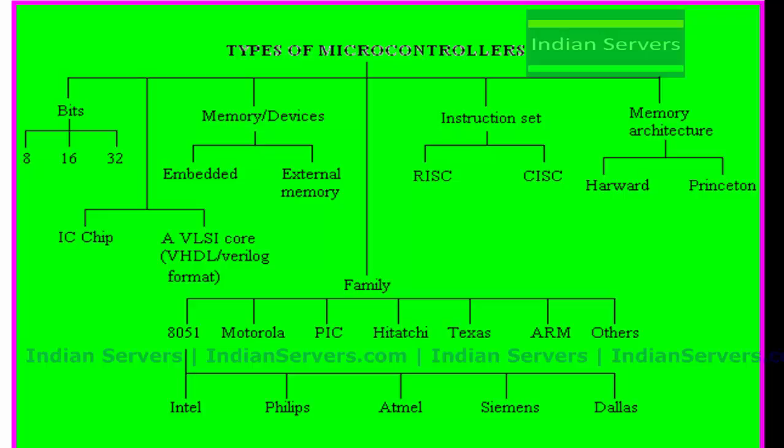Coming to RISC, we can easily program a controller or an embedded system. The instructions are very easy to understand. If you take CISC, the instructions become complex. The best example for RISC is the 8051 microcontroller or other AVR microcontrollers. They are all prepared using RISC architecture, so programming these controllers is very easy.